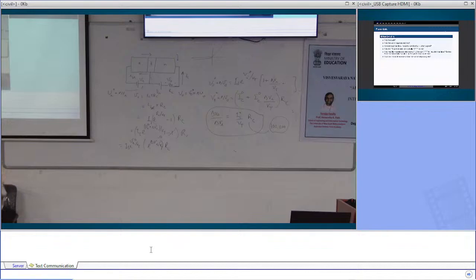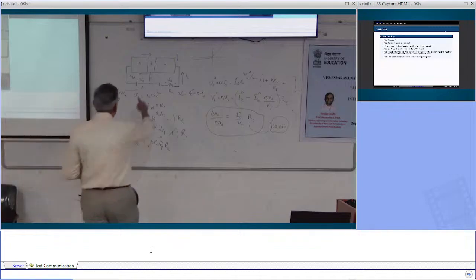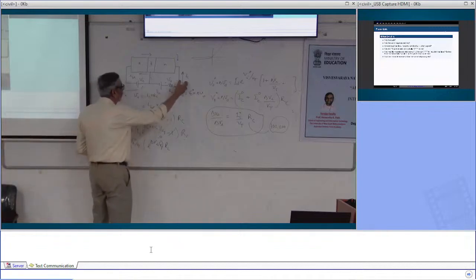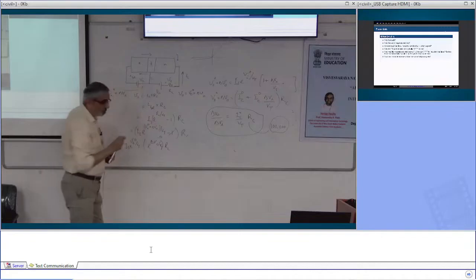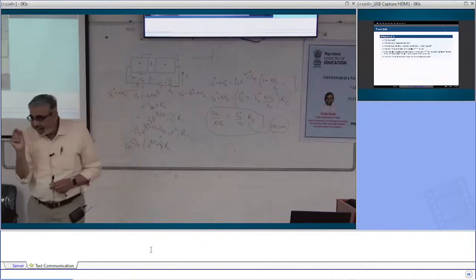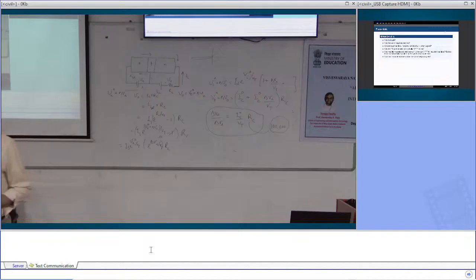The whole idea is that this side of the circuit, it does not matter what current is flowing, it will be exactly the same as that current. And that current can be changed by a large amount by a tiny change in the forward bias. And that large change, I am running it through the collector resistance RC to give me enormous voltage gains.